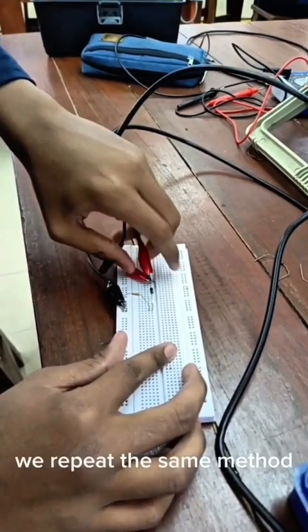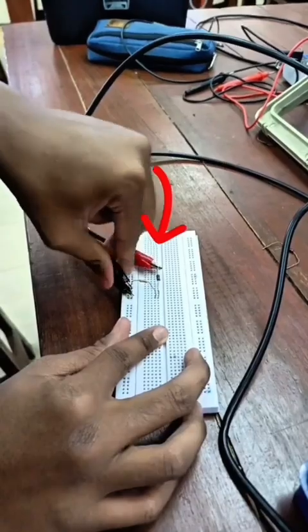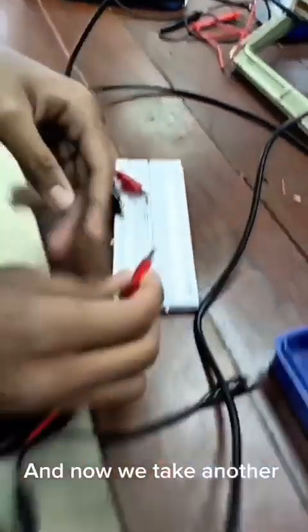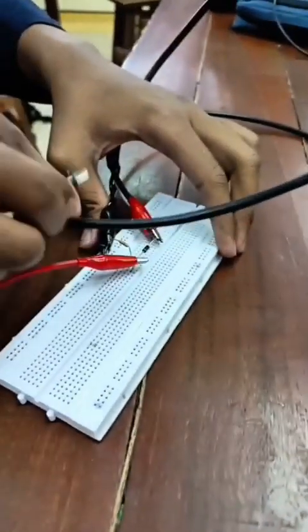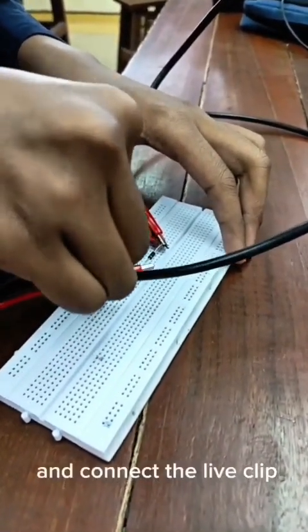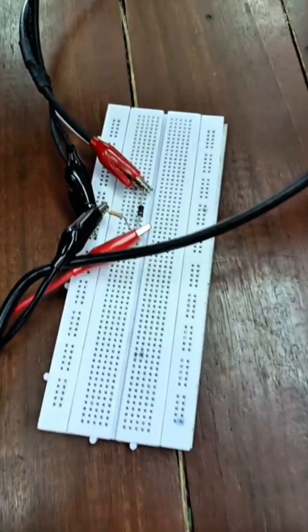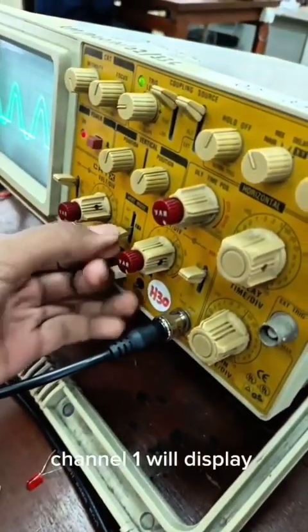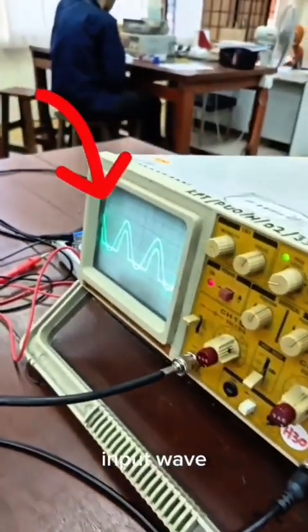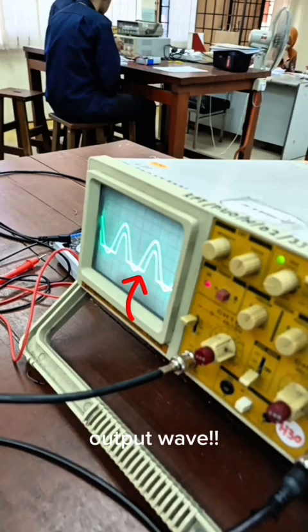Then, we repeat the same method for the function generator. Now, we take another BNC to crocodile clip and put it on channel 2 and connect the live clip to the opposite side of the diode. Then, put the neutral clip to earth. And now, as you can see, channel 1 will display the input wave and channel 2 will display the output wave.